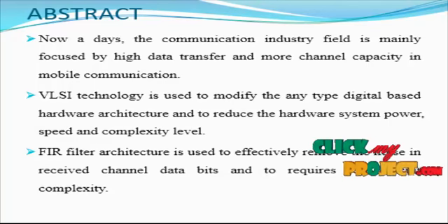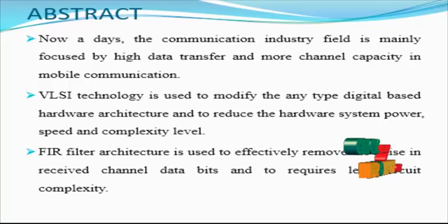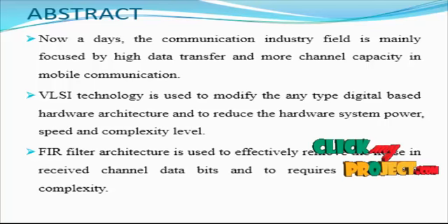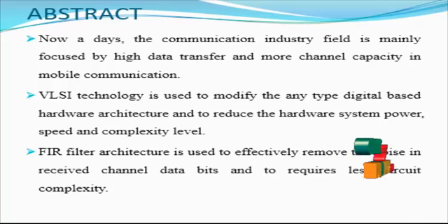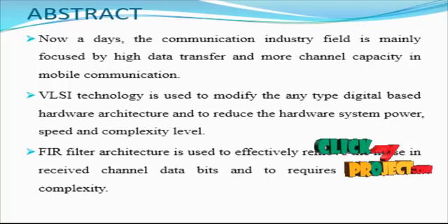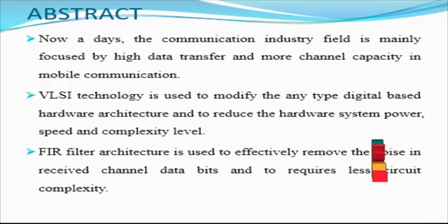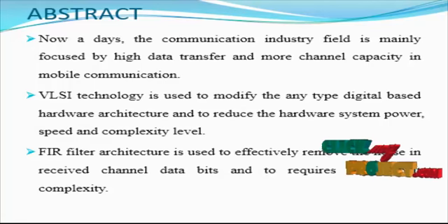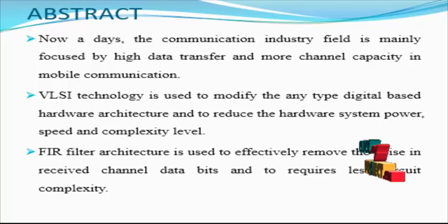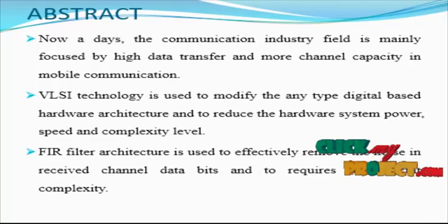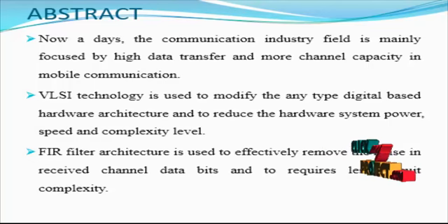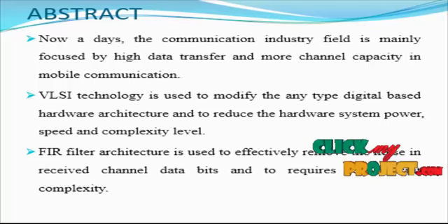It's important to minimize the net energy consumed by the system to maximize its lifetime. The energy consumption of the system can be reduced by lowering the supply voltage. However, at very low supply voltage, the leakage energy dominates and the net energy consumed per operation starts to increase. The minimum energy point depends on the activity factor and is also sensitive to process and temperature variations, and therefore the location of the MEP changes during circuit operation.